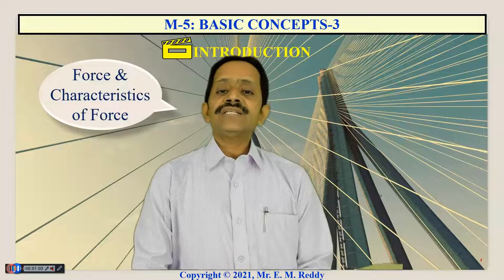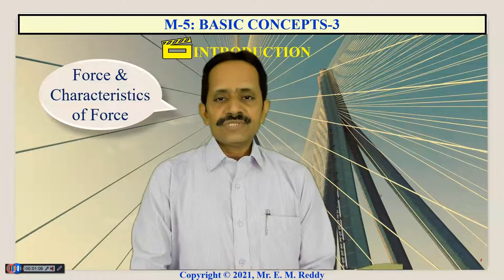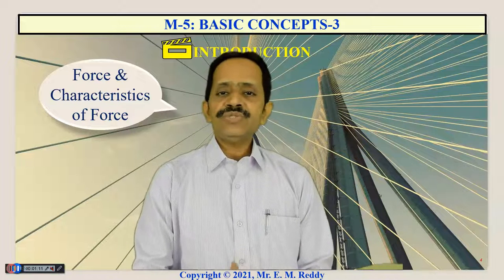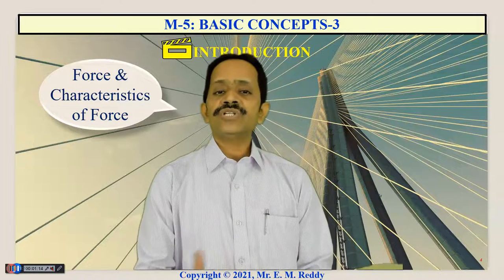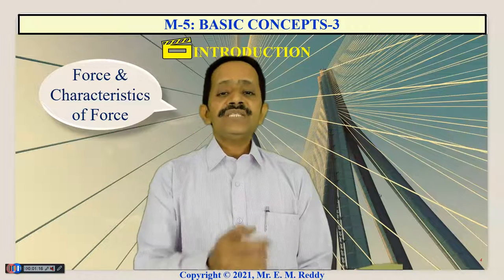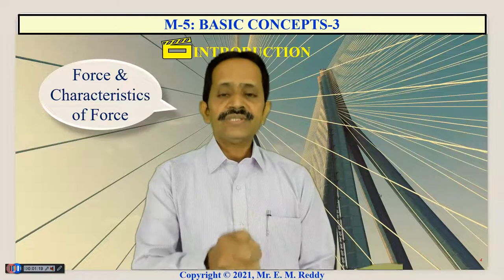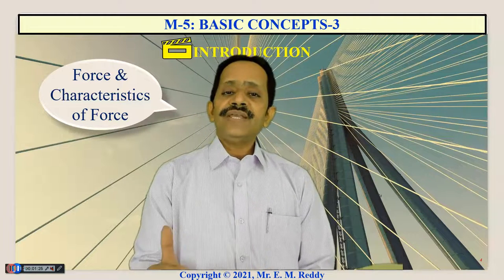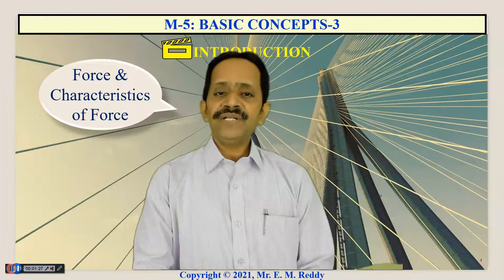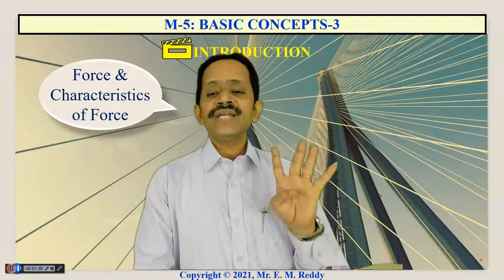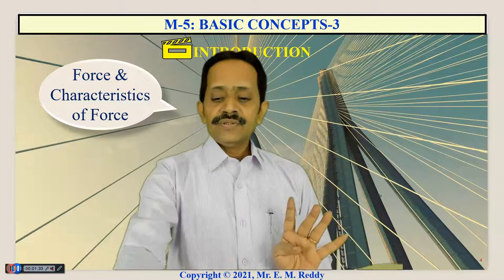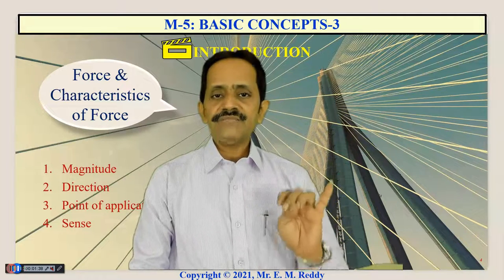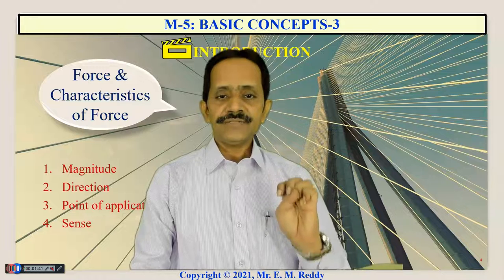Force and characteristics of force. What is force? Force is defined as an external agent which tends to change the state of rest or motion of the body. Simply, it is a pull or push that results from an interaction between the two bodies. To describe the force completely, we must know its four characteristics: magnitude, direction, point of application, and sense.